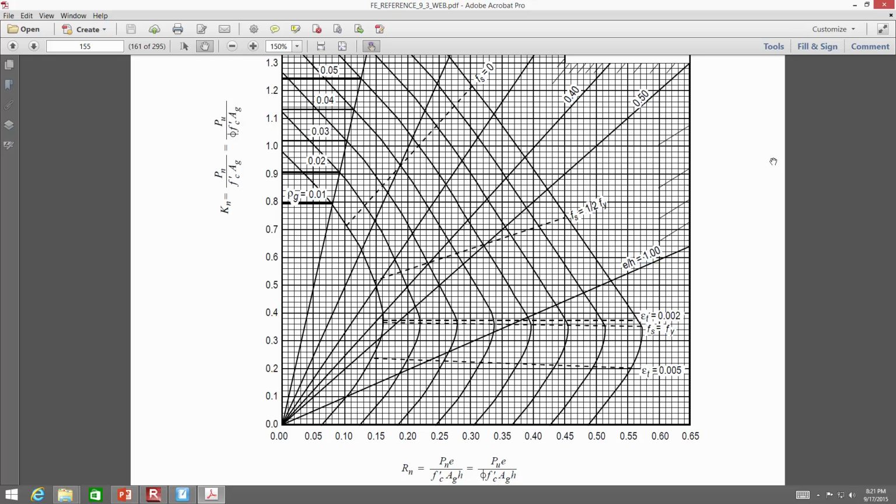Yes, that's why the chart is limited. In fact, they have to sort of be between that. Yes, yes. You have too much steel, and you can have crushing and stuff like that. Not enough, and then you don't have enough ductility.